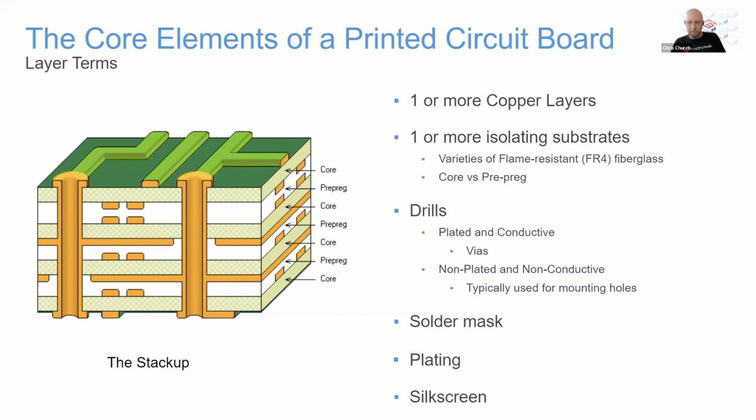So what we'll do here is plate or coat those exposed copper pads that things are going to be soldered onto. And very common, what you'll hear a lot, one of the most common ones is HASL, that is hot air solder leveling. So what they'll do is put solder paste on all those pads and then hit it with a hot air gun. The idea being that will melt that paste and cause it to flow around and self-level a little bit.